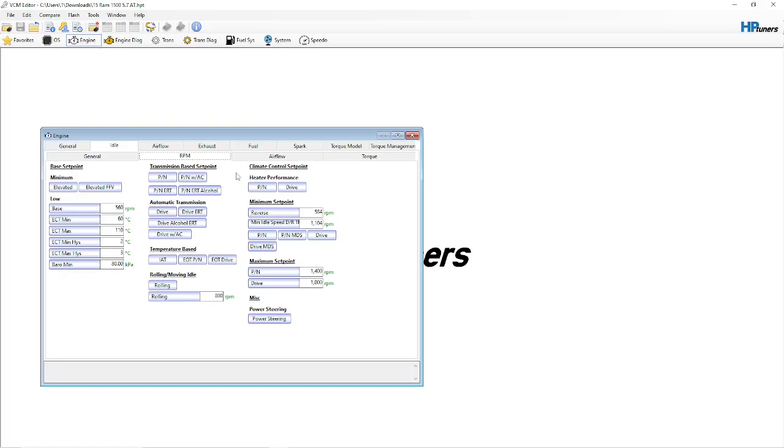The engine can have wear in it. It can be having engine oil consumption. It can have low compression. The freaking list goes on. So that's why flash tuning is really unviable, and even e-tuning really is entry level. A base map is where I consider those at, your flash tunes and your e-tunes, because all you're doing is pretty much getting the vehicle operable.